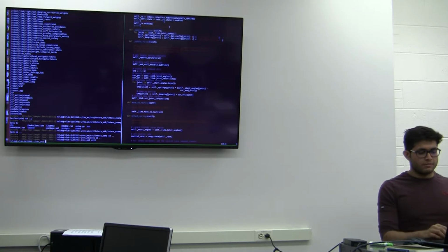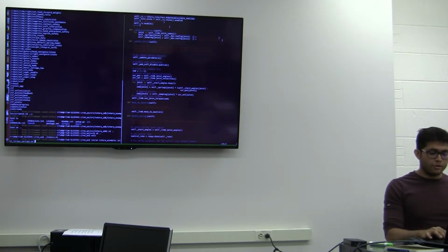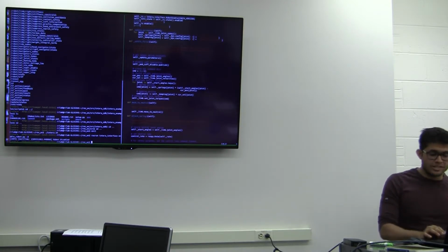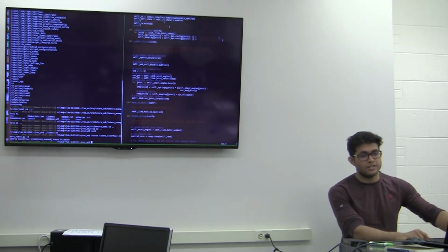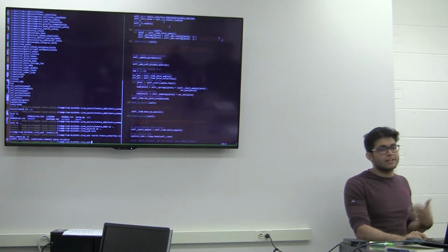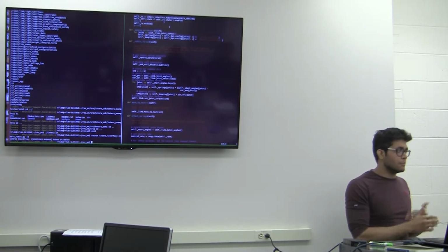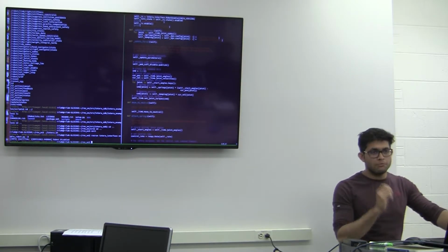So now I'm outside that script. I ran that script again, ./intra.sh. That's it. But again, before anything else, before closing this robot, make sure you disable it. If you don't do it, we are going to have a lot of issues. If you just don't disable the robot and switch the power off, it's going to save those things as errors, and it might not give us errors initially, but with time there might be default errors accumulating here. So every time please make sure that you disable the robot first before closing it.